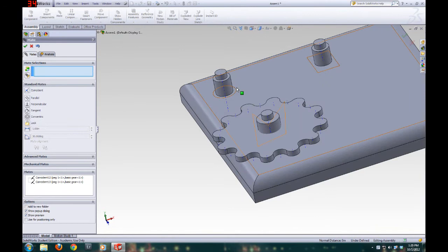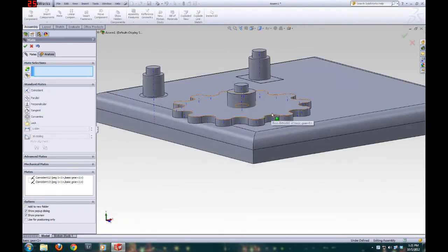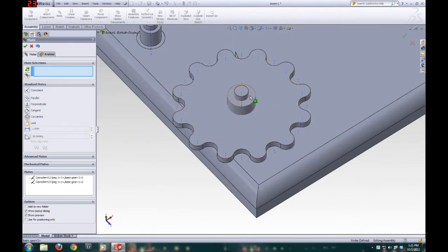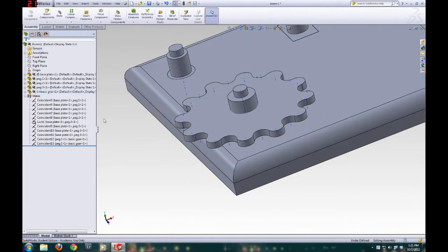So what do you do if you establish a constraint incorrectly? You see that SOLIDWORKS accepted the constraint because it's not necessarily looking at geometric interference at this point, although that is possible. We'll cover it next week. It has created an interference between these two parts because obviously the half-inch hole in the gear is not going to fit around the 0.75-inch offset boss. But we've already accepted the mating constraint. We can close it out.